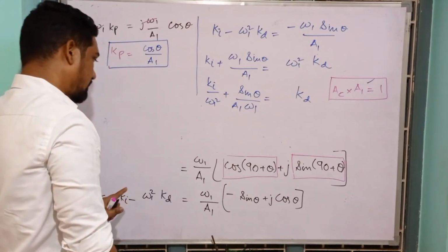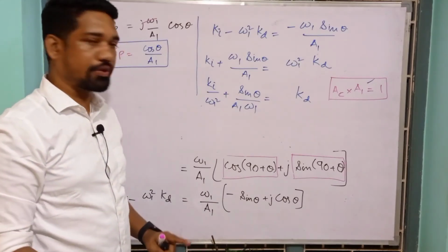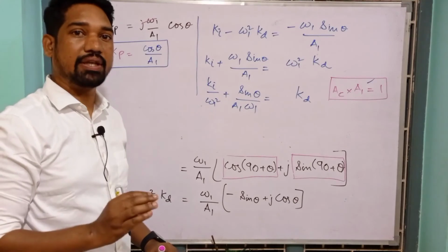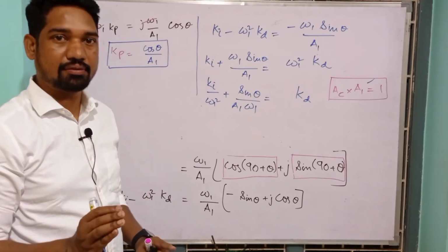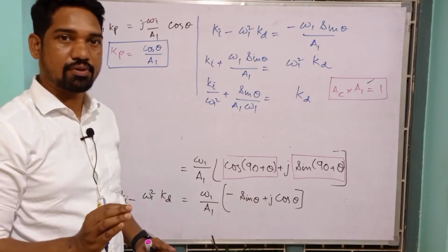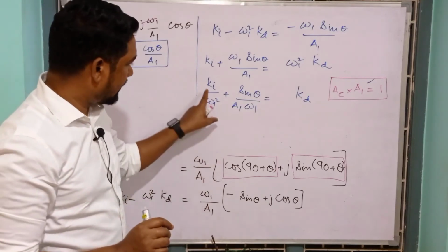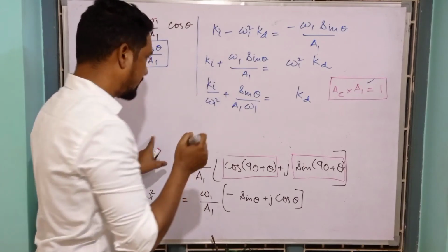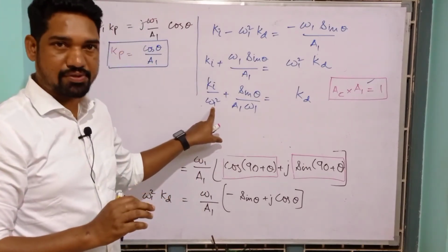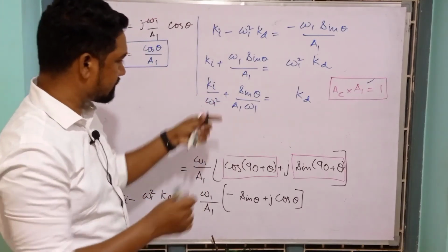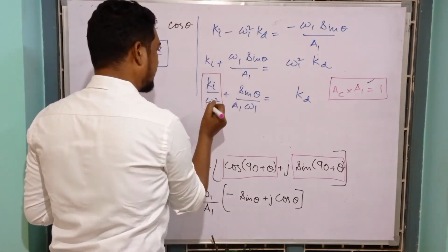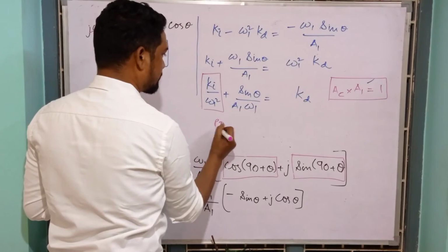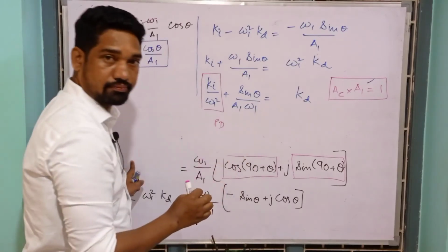So guys, an important point to be revealed over here. If you have to evaluate only PD, proportional plus derivative controller, ki should be assumed to be 0. We don't have this term, so this term is made 0 if we have to design only a PD controller, making use of this expression, right?